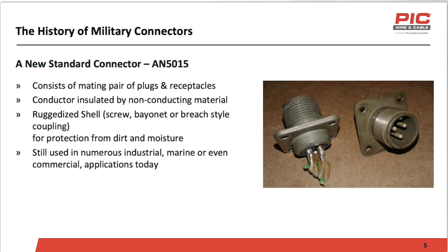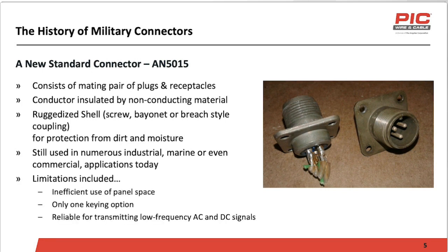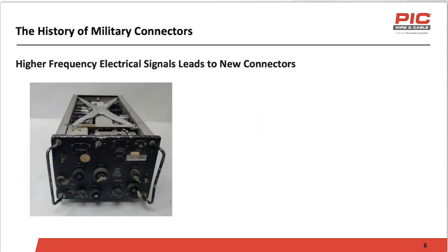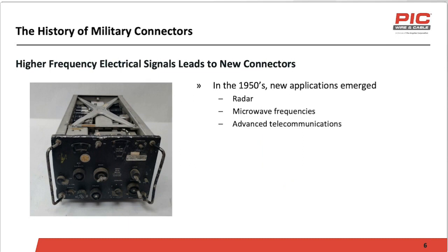While the AN 5015 connector proved to be a very reliable connector for its intended use, it was only available in a single keying option and took up a large amount of panel space. As newer applications began to emerge, such as radar, advanced communication, and microwave frequency technologies, the need to transmit higher frequency signals arose.